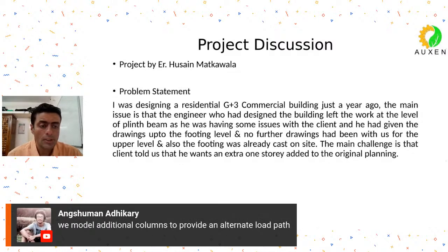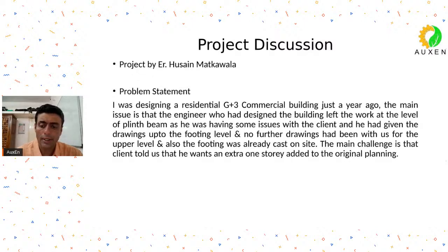So Mr. Amshuman is saying that we may provide additional columns to provide an alternate load path. Additional columns will be a problem because then you will have to compromise with the planning. So that might not always be agreeable to the client to add more columns. So in case the bearing pressure of footing exceeds, then you don't have any other choice but to excavate.